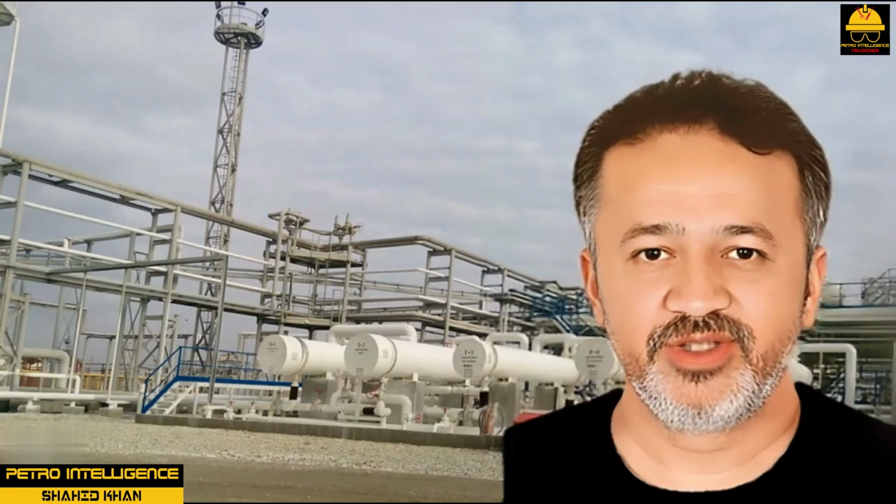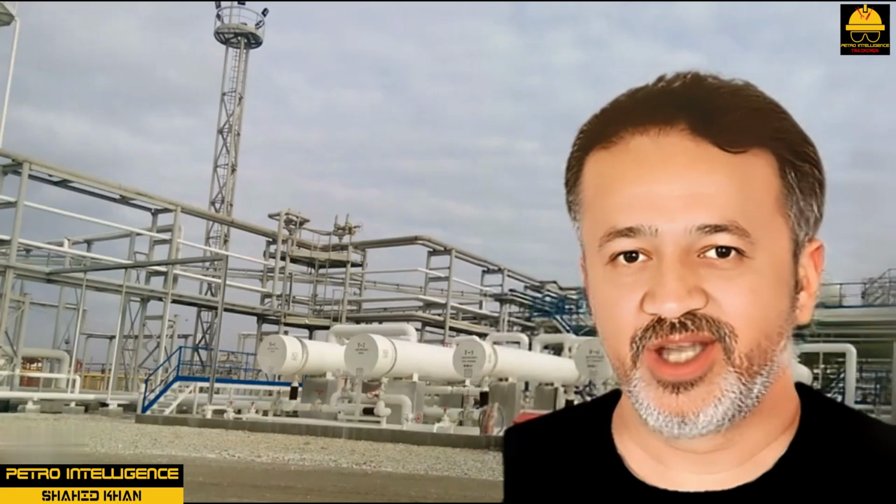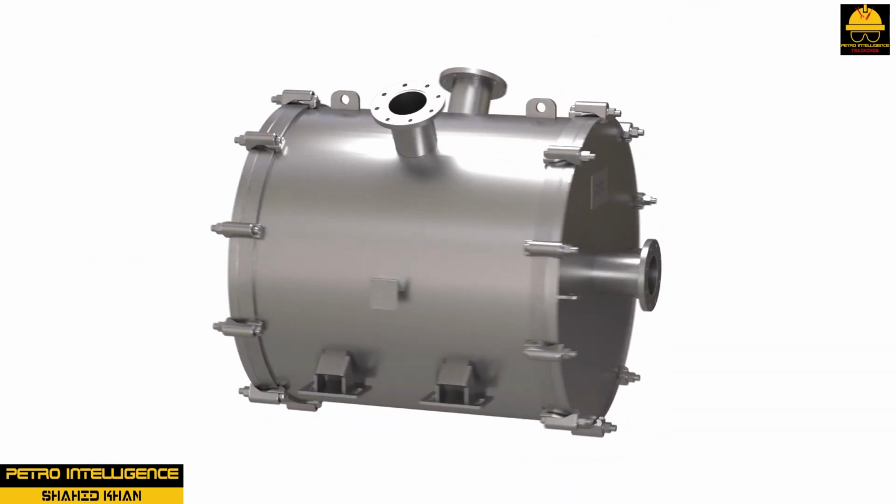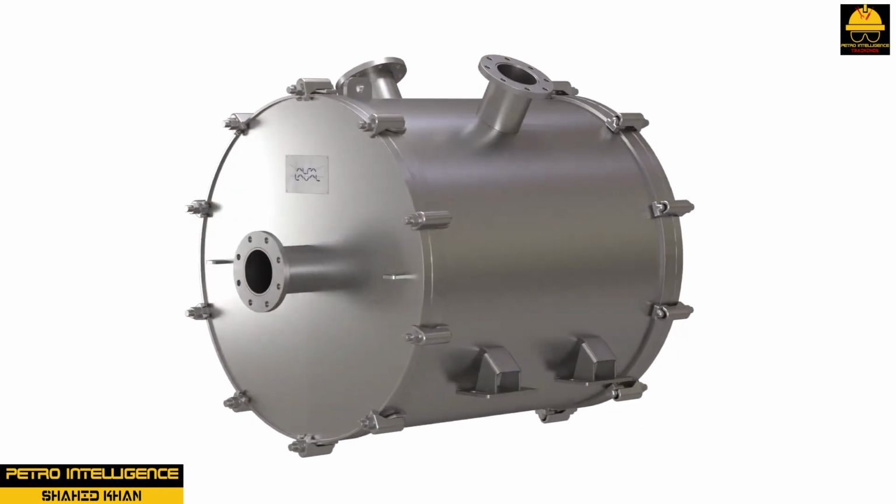Spiral heat exchangers. Spiral heat exchangers are characterized by a compact concentric design that generates high fluid turbulence in the process medium as shown in picture. This type of heat exchanger comes in two basic types: 1. Spiral flow on both sides, and 2. Spiral flow cross-flow. Type 1 spiral exchangers are used in liquid-liquid, condenser, and gas cooler service.